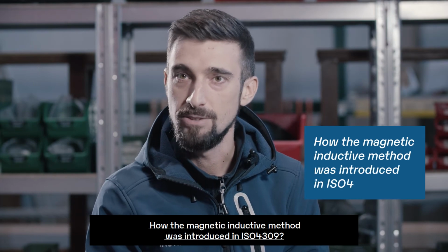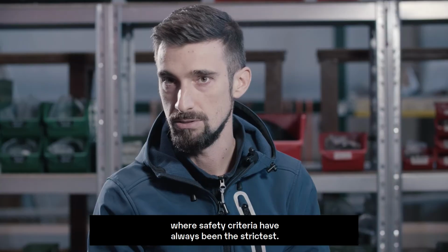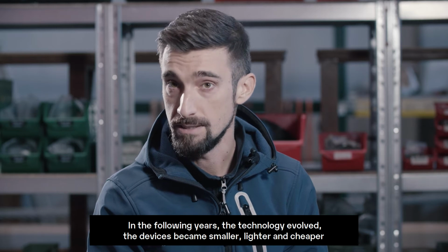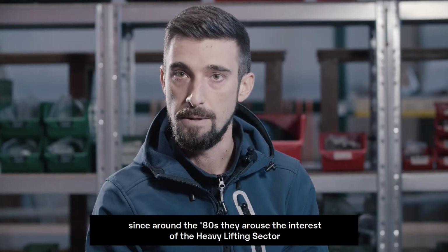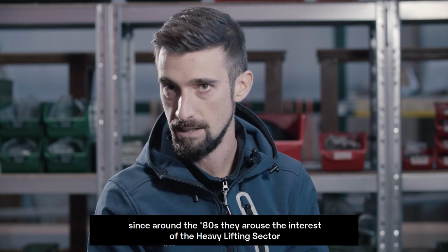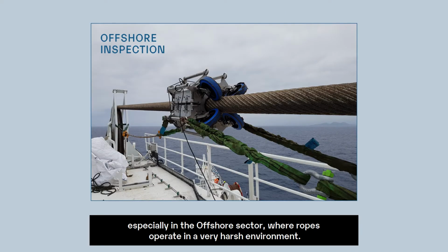How was the magnetic inductive method introduced in the ISO 4309? The magneto-inductive method was born at the beginning of the 20th century in the ropeway sector, where safety criteria have always been the strictest. In the following years, the technology evolved. The devices became smaller, lighter and cheaper. Since around the 80s, they aroused the interest of the heavy lifting sector. Since the early 2000s, the technology began to be used widely, especially in the offshore sector, where ropes operate in